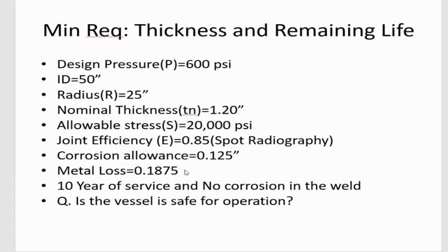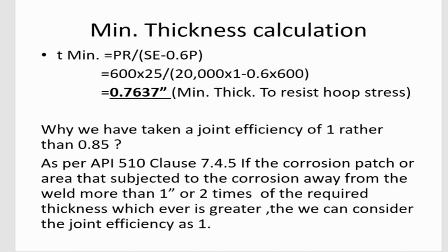Metal loss is 0.1875 inches after 10 years of service, and no corrosion in the weld is observed. The question is whether the vessel is safe for operation or not. And also we have to find out the minimum required thickness and remaining life.